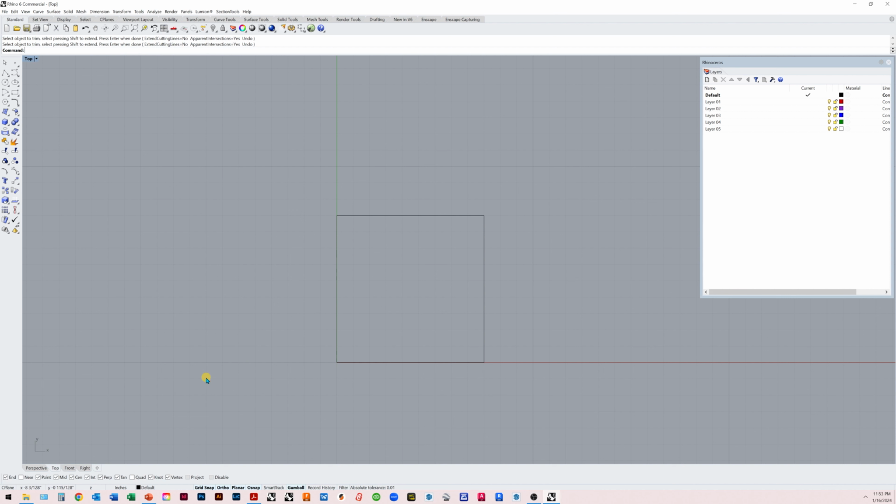So that is great. Now, the next thing we want to do is make the grid inside of the box. To make the grid inside of the box, what we need to do is copy this line over a bunch of times, 1 inch by 1 inch by 1 inch. I'm going to show you 2 different ways to do that. We can use that copy in place again. So we can click this line, and copy it in place. Let's right click. And then we can use the gumball. And here, instead of typing 9, let's type 1. Okay. Now we've got 1 inch.